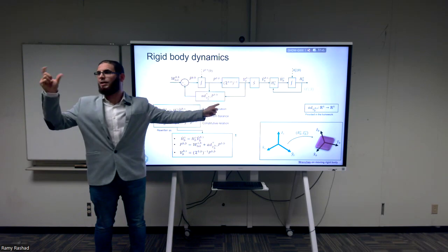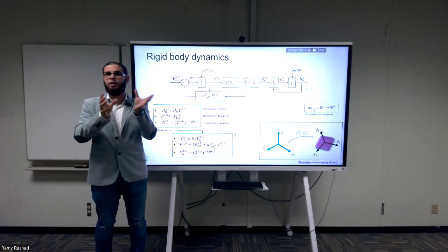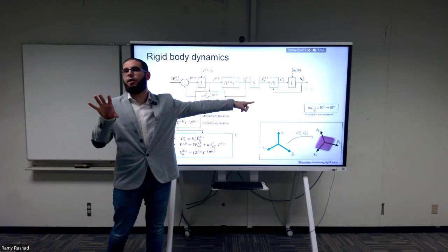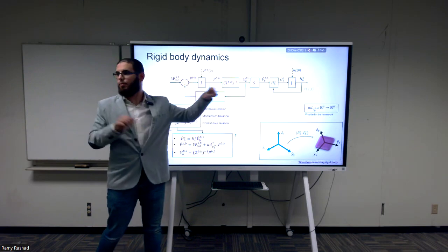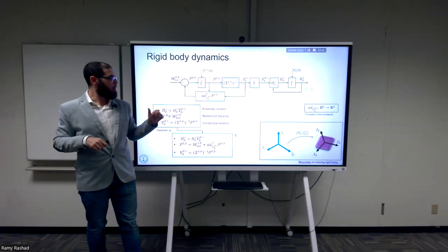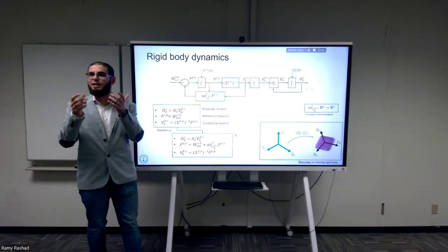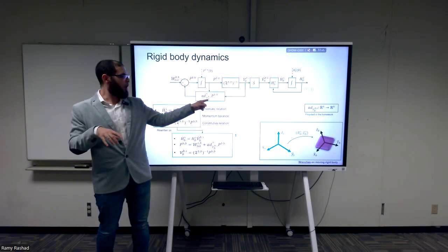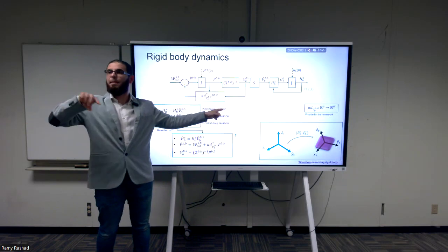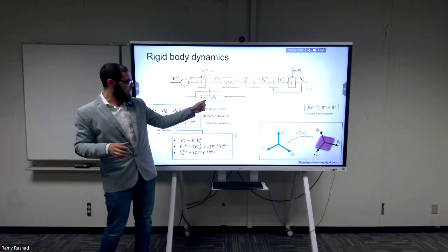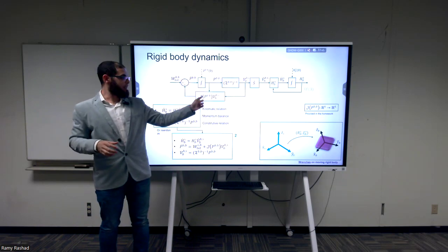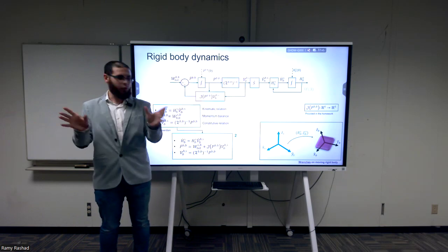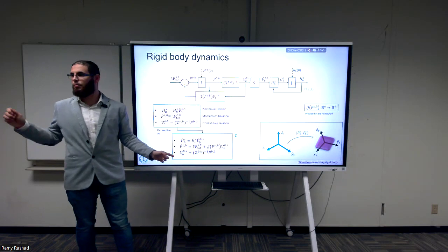Just like if you go back to the angular momentum and the angular velocity, you're going to find we had some coupling between both in this box. The precise map of this, we call it the adjoint operator of the algebra. You're going to be deriving it yourself, and you're going to see it in the homework. I can play around with the matrices or use some deep insight to rewrite this. We can rewrite it as, instead of a map of the twist multiplied by the momentum, I can write it as a map of the momentum multiplied by the twist. And again, I can rewrite it as a map of the momentum like this. This has also a very nice property that actually this map is skew-symmetric. Again, more on this later. Just two forms of the equations. You're going to be proving them yourselves.